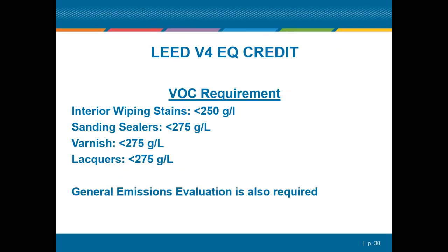The term crosslink is often used for solvent-based products. Can you please define this term? Yes. Cross-linking, there are a couple of different ways. There are some things that are called pre-catalyzed, and then there are some things that are cross-linked or catalyzed. The pre-catalyzed products, we have those in a wealth of different kinds of products. There's a catalyst aspect to those that is already added at the factory, and they are ready to apply.